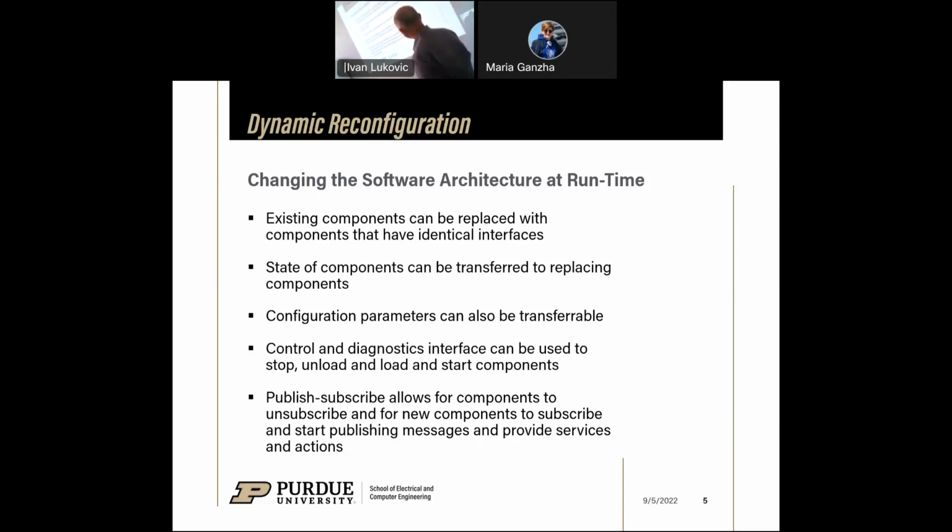All these things that I've talked about so far could be worked out very easily in the publish-subscribe architecture that I described in the previous presentation, for example in PX4, or ROS or ROS2, which is the very popular Robot Operating System. Publish-subscribe is really good because it has this loosely coupled model that people in computer science like to talk about, and it pays off in building extendable systems. They don't make weird dependencies. When you remove one component, you can put in another one without disturbing the rest of the system.